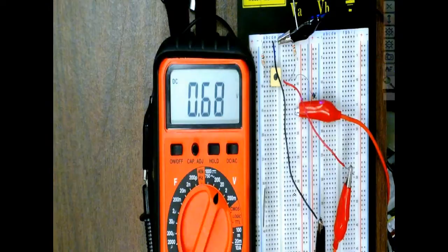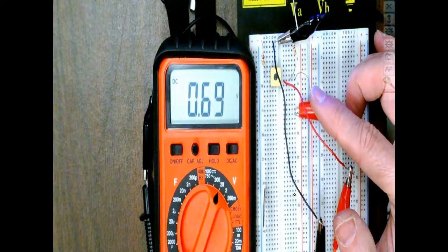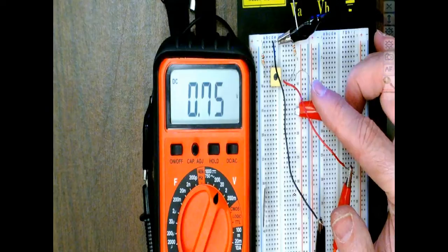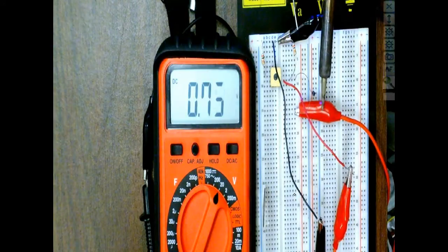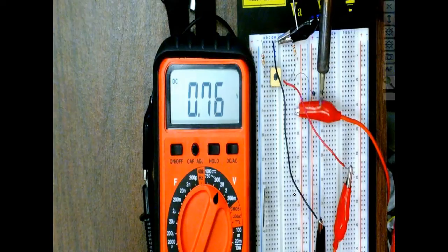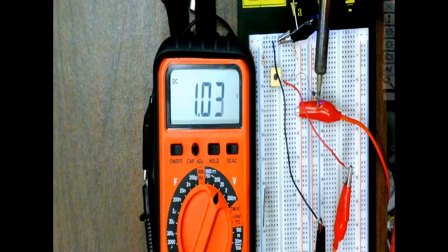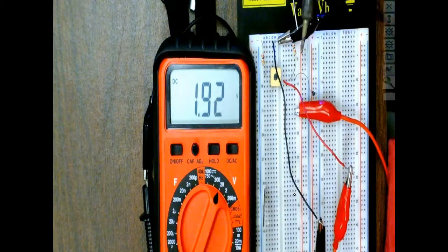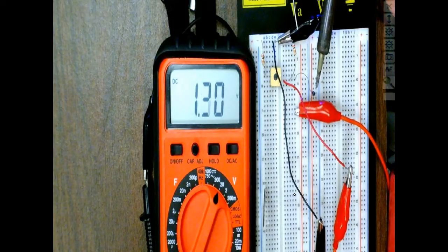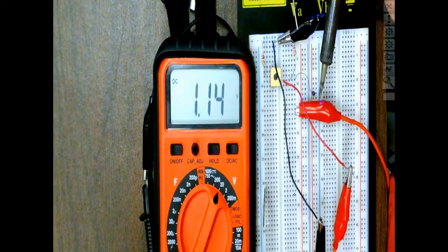Now what should happen is when I heat this up, the voltage should go up. And when I let it cool down, the voltage will go down. And of course, here's my soldering iron now. I'm going to bring it over here. You can see I'm not touching it, even though it appears I am, because that would be melting it. So now notice the voltage is going up because the resistor is at the bottom. The fixed resistor, this is common. There's my black lead off my power supply. So now I've turned an NTC into something that gives me a positive voltage when temperature goes up.